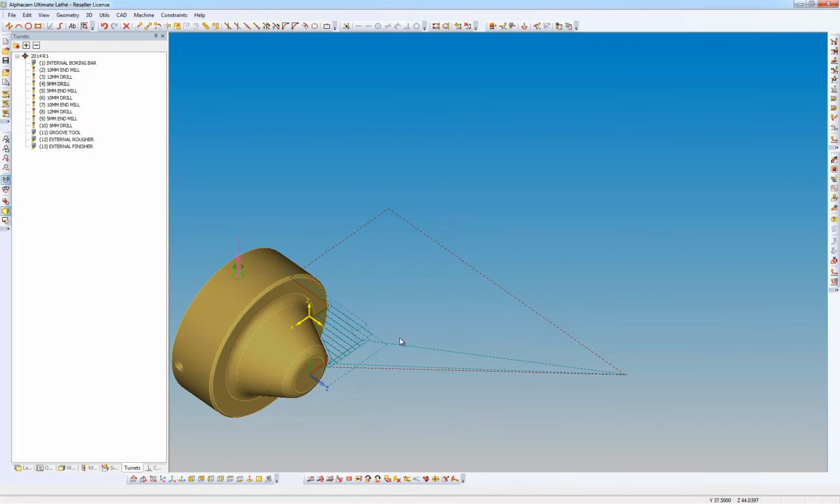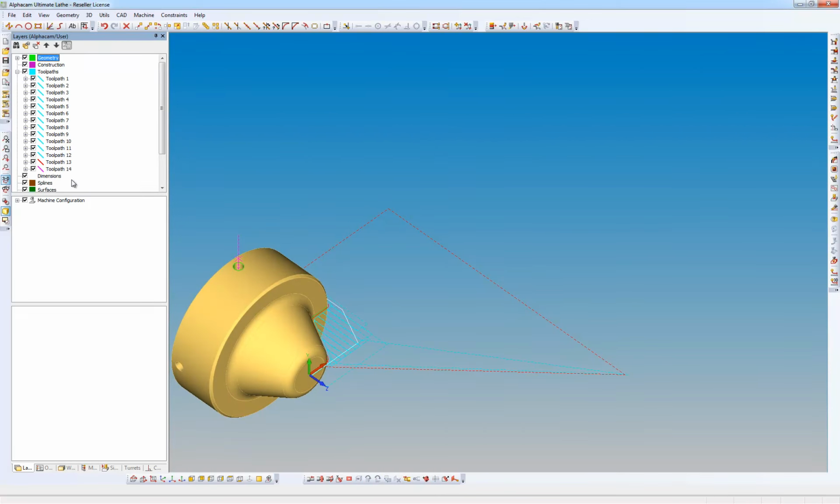So what I now want to do is rotate this, so I'm going to cancel the work plane. I'm going to select the tool, the tool path from the project manager. So I'm going to use the rotate command, which tool path I want to, and I can see the color is the same. Linear axis of rotation, revolution, angle of 90, and how many copies including the original? 4.